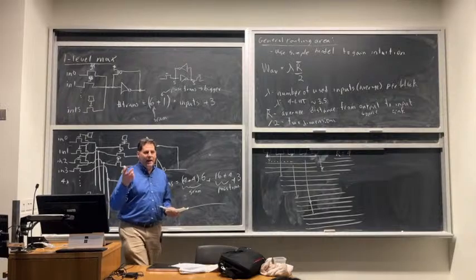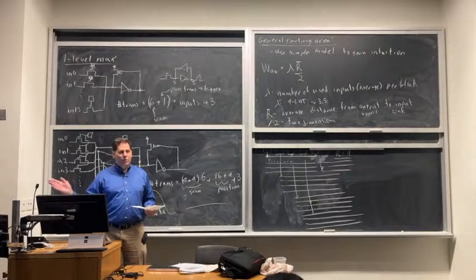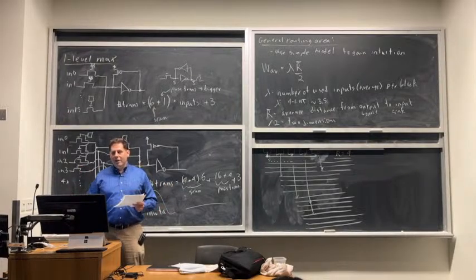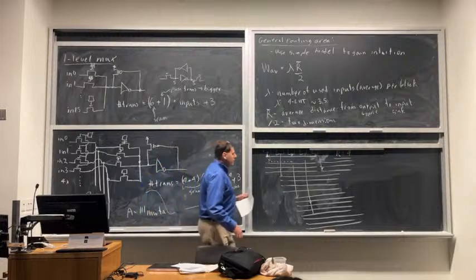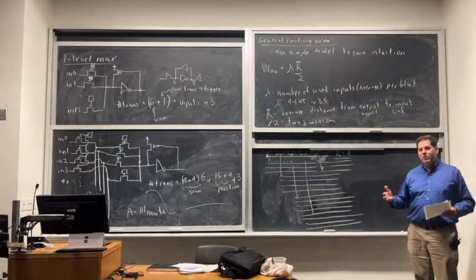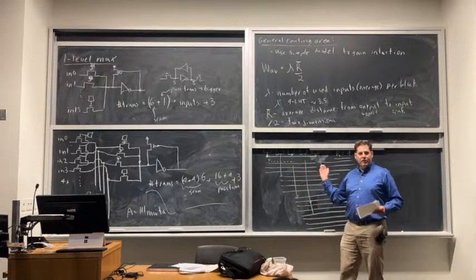Because the switch patterns, we have limited switching between wires, right? We're not connecting every wire to every other wire with full crossbars. Remember back when we looked at our various styles of logic element and switch network, we said full crossbars aren't scalable. You just can't connect everything to everything, and as your crossbars get big, that gets really inefficient. So FPGAs use smaller muxes. There are a whole bunch of limitations on which routing wires can connect to each other. So you can't actually use all the routing wires in a channel.